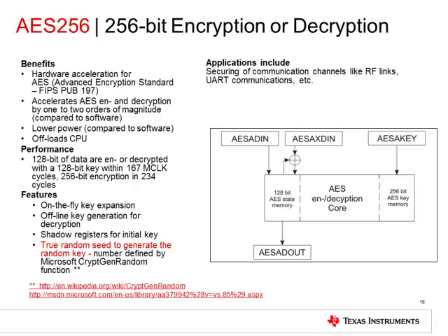The AES accelerator module performs encryption and decryption of 128-bit data with 128, 192, or 256-bit keys according to the Advanced Encryption Standard. Some key features of this module include the ability to perform 256-bit encryption and decryption in 234 cycles. In comparison, a software algorithm takes a few thousand cycles to accomplish the same. The module also allows DMA usage for autonomous operation and provides an AES-ready interrupt flag once encrypted data is available.